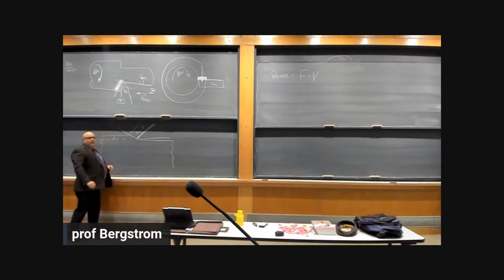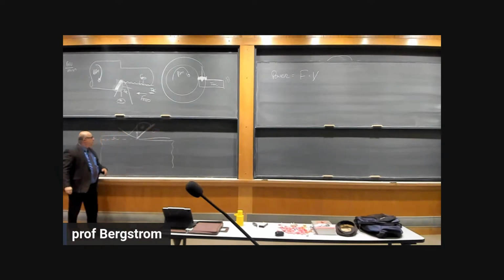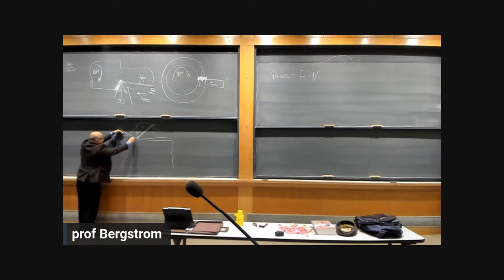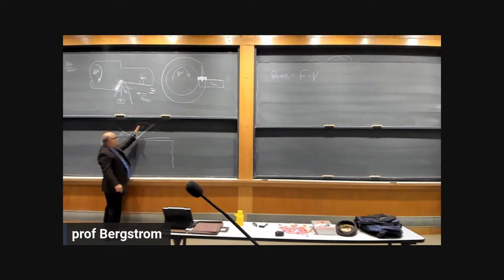We've got that shear plane. And we've got our rake angle, right? This is alpha. This is our rake angle. This angle here is our shear angle. As that shear angle changes, it's going to be impacted by the bulk properties of the material, right? It's also going to be impacted by our rake angle. Does that make sense?